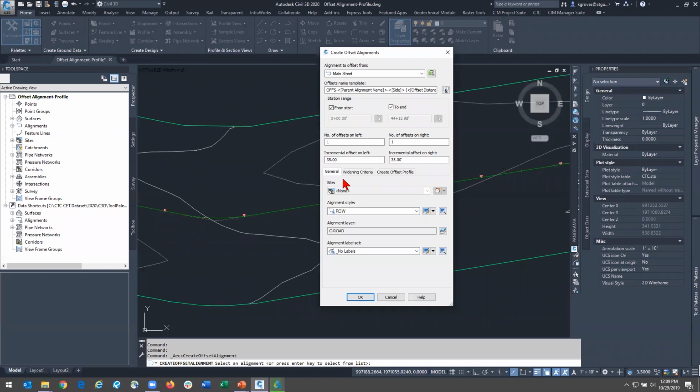Visually, you can always use a mask to cover up those in your plan display if you don't want to see them. But it is important that you can determine multiple rows or no rows of offsets on either your left or your right side, and then your distance away from that would simply be what you're defining down here. So if I'm going to be doing this first round as the ETW, sorry, I keep changing my mind here. But at the edge of the travel way for this particular roadway, I'll go with a 12-foot wide lane before I start my curb, and so on and so forth.